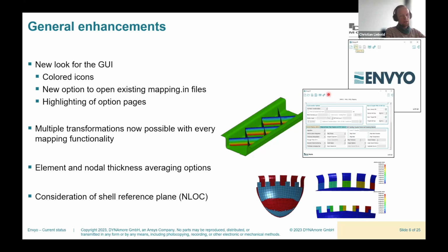But at least in my experience, and I always have a dedicated developer view onto things, once I have created a mapping.in file for a dedicated use case, which you usually use once in a while and is a repetitive procedure, you just change the number of integration points or the file name, and then you should usually be good to go.